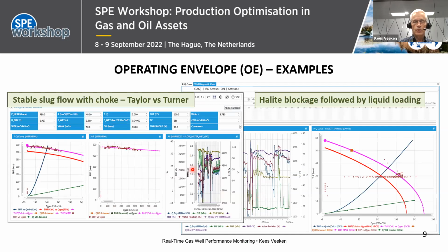Now let me show you a few examples using the same web-based tool. On the left-hand side, the picture is your PQ plot. Purple again is PQ, and the red is your warning at 95% of reservoir pressure. And you see the liquid loading line and the erosional line. The center plot is the calculated bottom hole pressure data plotted against the IPR that we assume. On the right-hand side, you actually see the time-based plot, the real-time data plotted across the time interval that you're looking at.